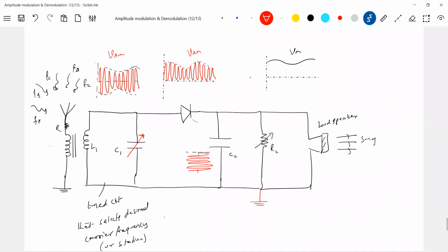The carrier will be there. So shall I call this a filter? What it's doing is eliminating high frequency and allowing the low frequency signal, the modulating signal. Since it has some DC voltage, I'll bring in some DC circuit which will nullify the DC voltage, and finally we get the required signal of this kind.